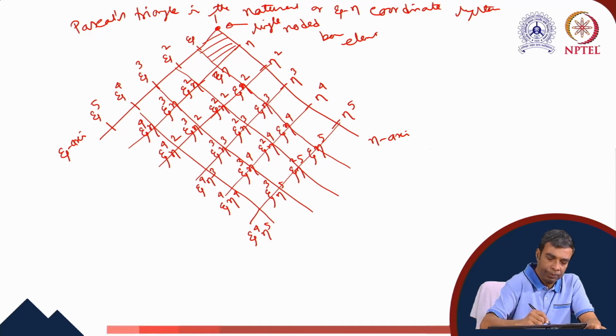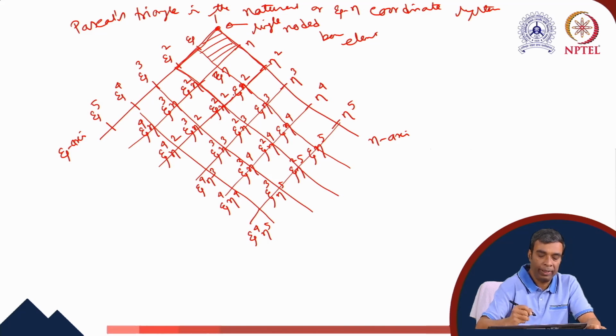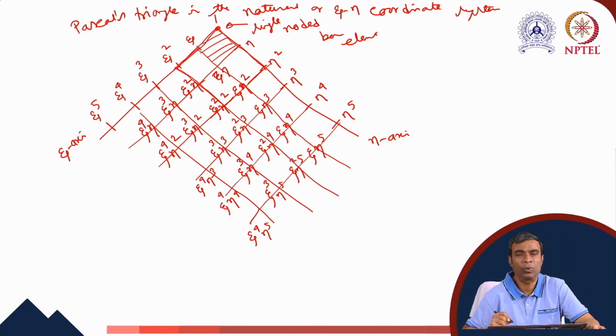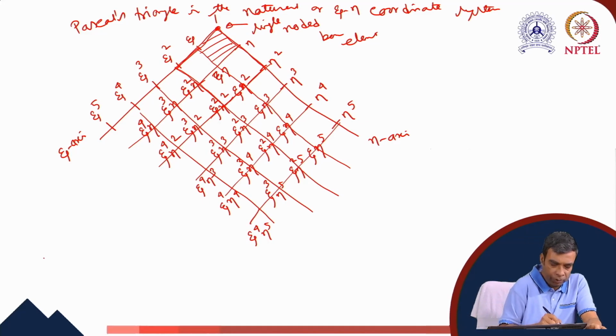So this will illustrate the quadratic quadrilateral elements where we have 9 nodes. So we have identified the nodal locations. Now using the quadratic shape function for the bar elements, we can construct the shape functions for the quadratic quadrilateral element. So use the shape functions